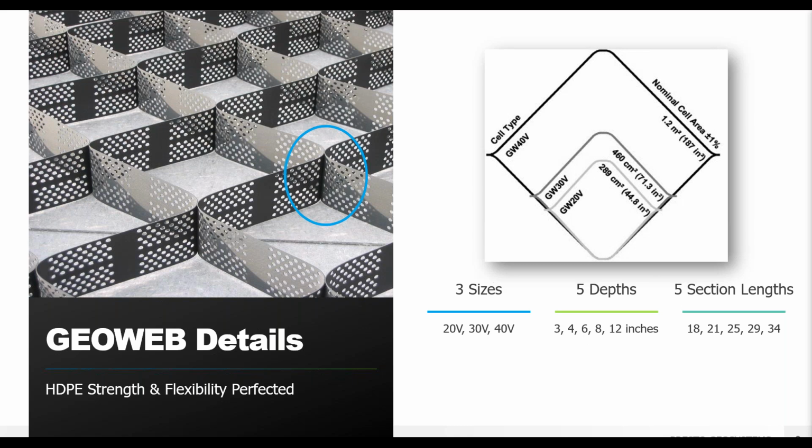Those fillers and alloys are usually offered in some of our competing products in the name of increasing cell wall stiffness. But you do want to avoid that because you don't want weld failures or differential settlement. And that can happen if you increase just the cell wall stiffness to the detriment of your welds. So what you really want is uniformity in the performance across all elements of a geocell system, rather than focusing on a single parameter alone.